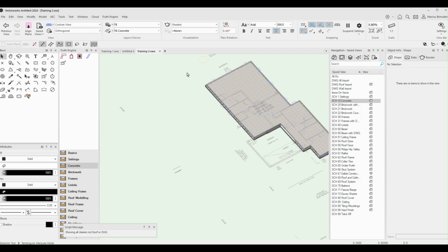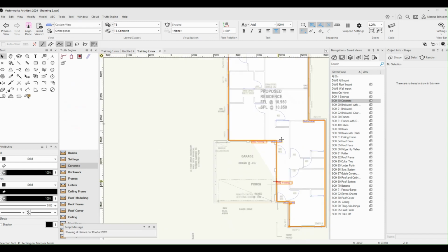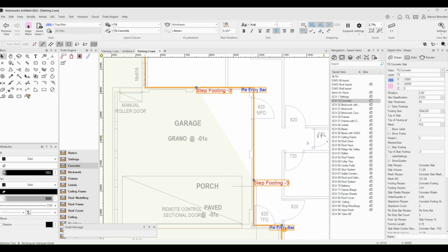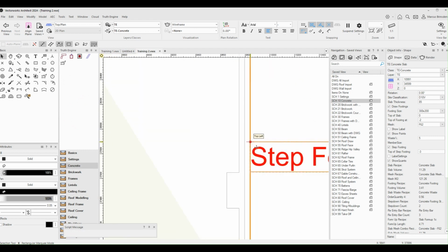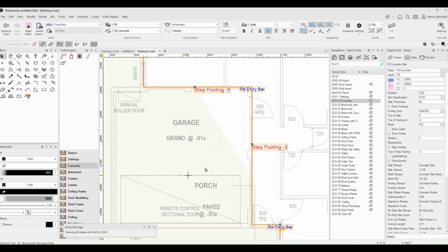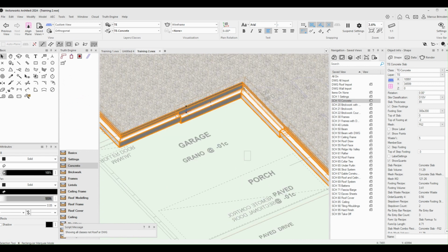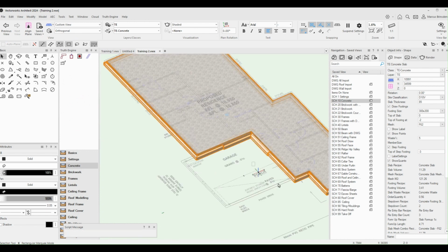So to do that, we'll go back to our main view, and you can see that I've turned on the step footing, and chosen the points, or moved the vertices and put it on the polygon to show where it stops and starts from. So if we go through the view, you can see there's our step. And that will work out the number of step down counts for your quants and also any extra concrete.